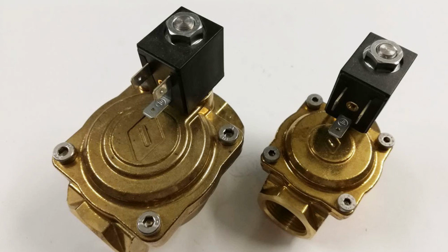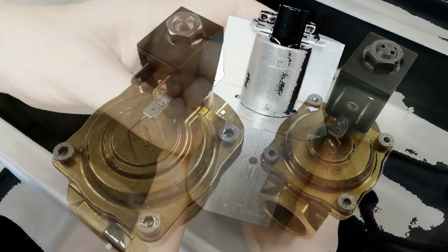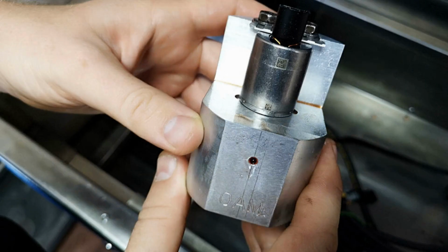Location. In order for the car owner to be able to check the current state of the solenoid valve, that is, the solenoid, he should know about its location. In fact, it is not difficult to find the desired element. The device is located in the hydraulic block. It is also called the hydraulic valve plate. The solenoid is inserted directly into a special channel in the hydraulic unit itself, where it is connected to the unit by bolt fixing, or by means of a fixing clamping plate. The other end is daisy-chained or plugged, which allows connection to the control unit.